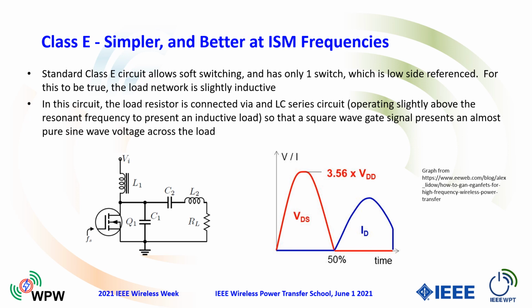And it does that with the resonant network here, the choke inductor L1, and by switching transistor Q1 at the fundamental frequency. So if I want a 6.78 megahertz current flow in L2, that's a sine wave, I simply gate the transistor Q1 with a 6.78 megahertz square wave, turning that transistor on and off in switch mode.